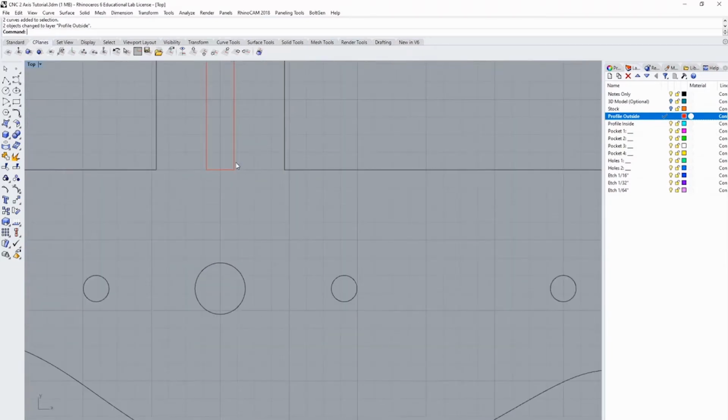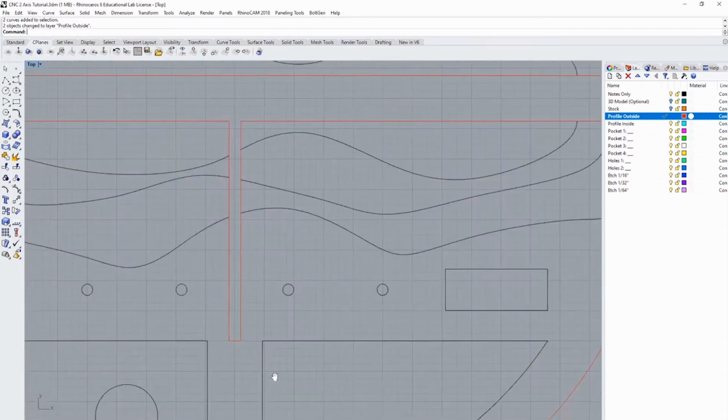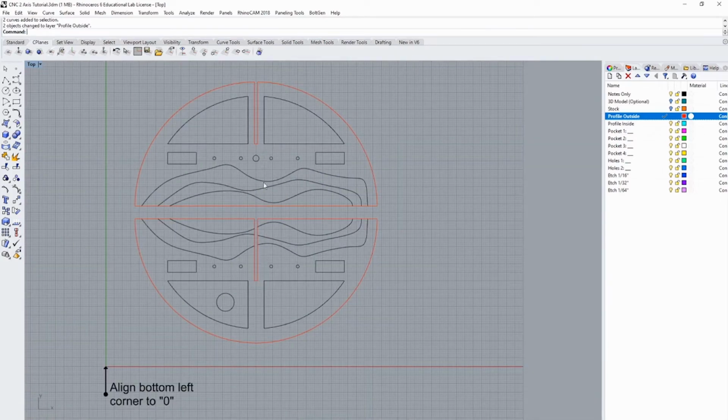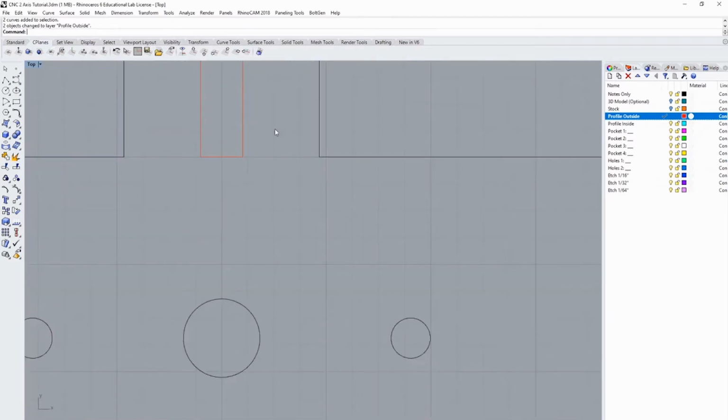One important thing to note with the CNC is that it cannot cut interior corners. It is limited to do that because the bit has a certain radius. So the smallest radius of interior corner we're able to do is 1/8 of an inch because that's the smallest bit that our CNC can handle. But I want these two pieces of geometry to notch together when it's done. A way to address this is to do what's called dog boning the corners. You'll see why it's called that in a second.